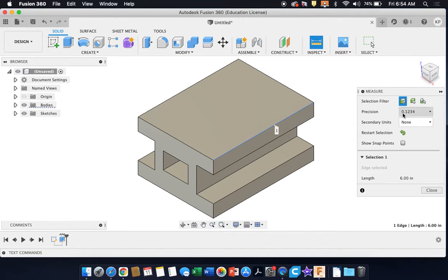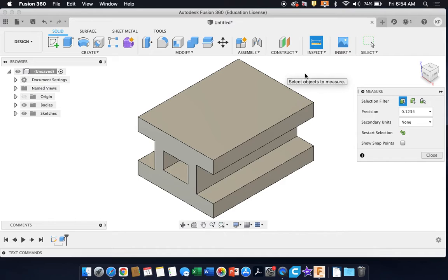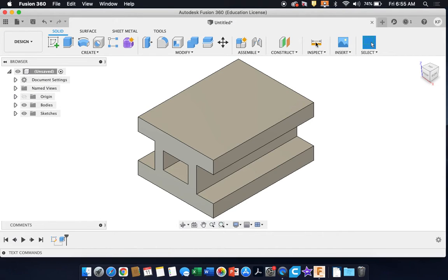So we can see that that's wrong. If something visually looks wrong, you can check it using that inspect tool. And you can click on circles, it'll tell you the diameter and things like that. So it is a pretty handy tool to have. But to fix this, there's only really one way to fix an extrusion, and you can use the same way to fix a sketch as well, but down here is the timeline.